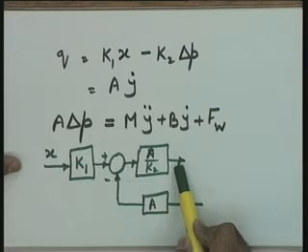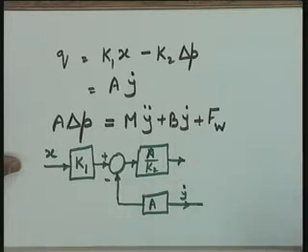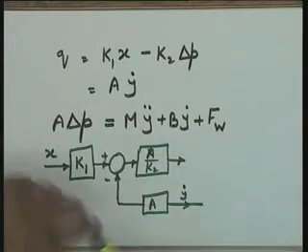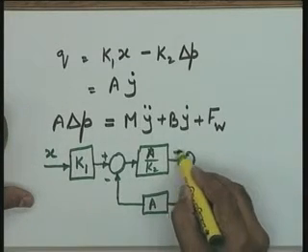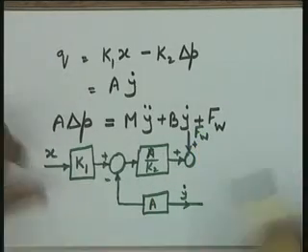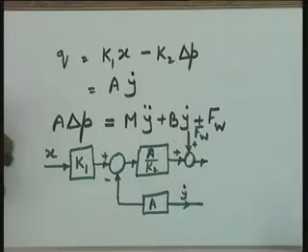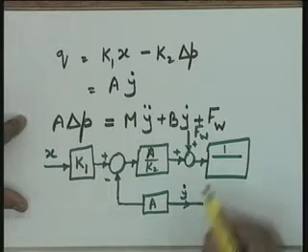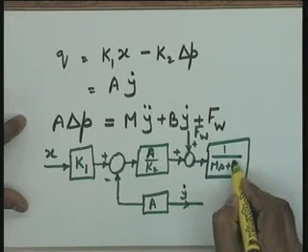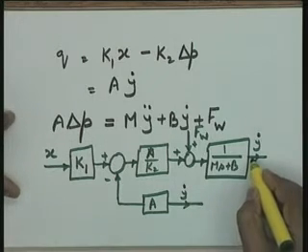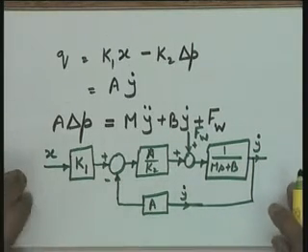In the tutorial classes, please recall, you have not been taking compatibility of units into consideration. That you have to keep in mind. I have the force variable, let us say in newtons. So I can algebraically add newtons to it, and Fw is in newtons, and therefore I can give the disturbance Fw here. So this is the net force to move the load, and the net force to move the load is going to be modeled like this: 1 over ms plus b. This is your y dot. Now you take this y dot and complete the feedback loop.